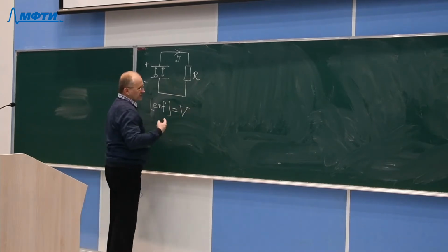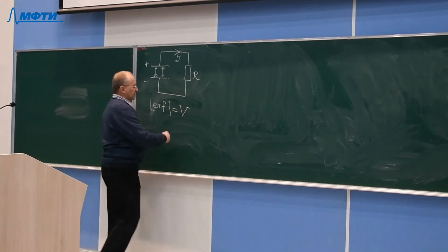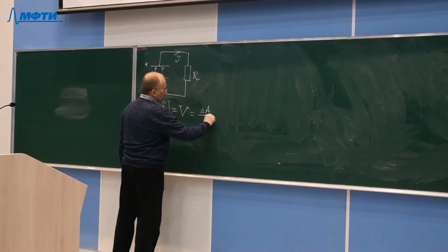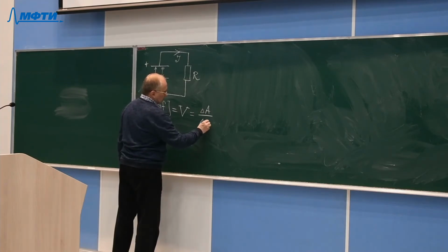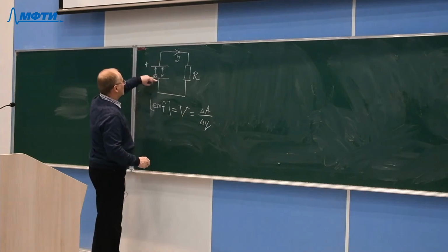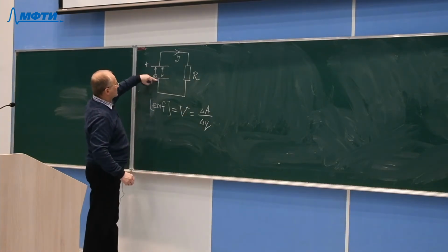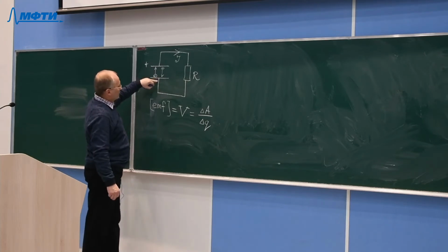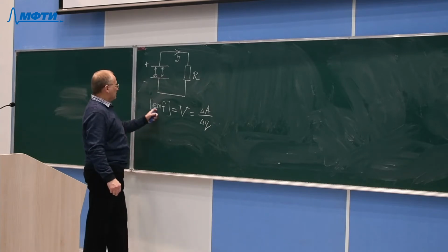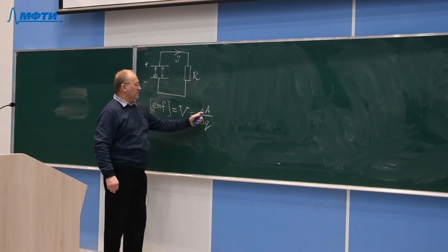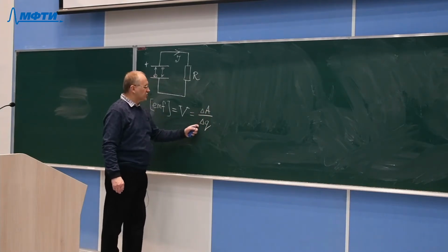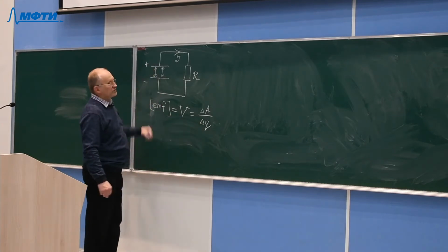And volt is a unit for measurement of potential difference, and by definition, a potential difference is the amount of work which is done in carrying some charge between two points, for example, between the two connectors where we measure the potential difference. So electromotive force is actually an amount of energy or work which is needed to carry a unit charge against the internal electrical field.